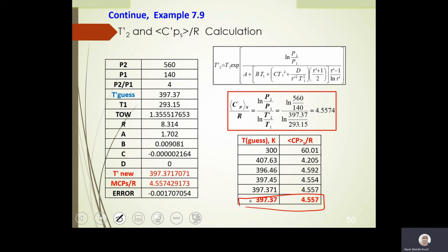you push it with another gas or compress it with another gas. So an ejector removes gases or vapors from an evacuated space and compresses them for discharge at a high pressure. So this is the idea behind it. But if you look at it, it looks like several nozzles connected together. So this is a nozzle here and that is a nozzle. In other words, ideally, if you applied the first law of thermodynamics to the nozzle here and then here, you should be able to find the properties needed. But that is not the real case.